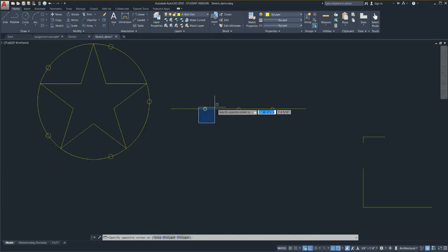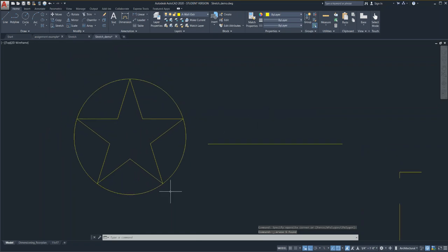And when you're done, you want to just select those points, those nodes, and delete them because they will print, which we don't want them to. Essentially, you just use them, and then when you're finished, you delete them, okay? So I'm going to delete these off of here so that they are gone, and I have my lovely circle with the star inside. And you notice that I am using a blue selection window to grab those, and now it looks the way it should.